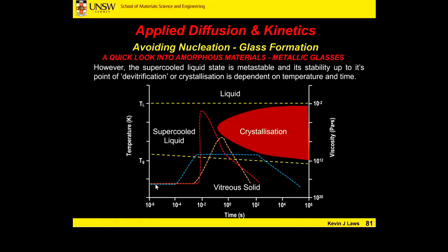And in this blue case, we're working very, very close to the glass transition temperature. So the viscosity here would be fairly high compared to this case. But we've got a very, very long time period that we can deform for. So it might be less complex, but we might be doing a very gradual, large deformation. We would heat it up just above TG, sit it at a fixed temperature, and again, this might be a limitation of our equipment.